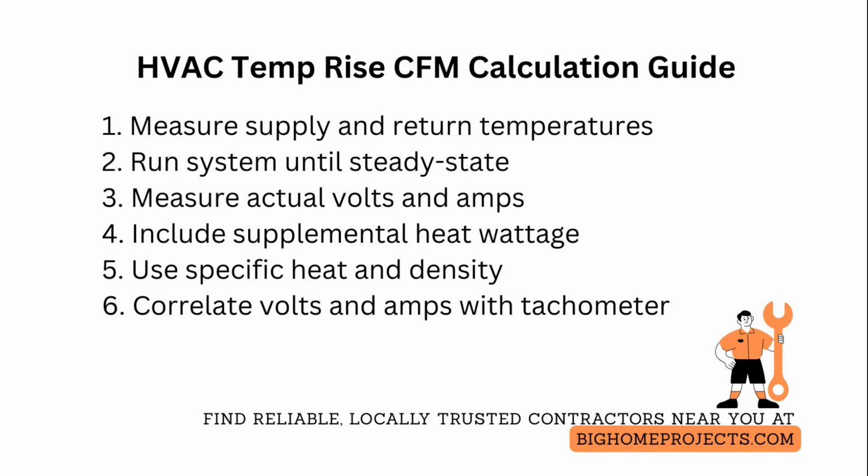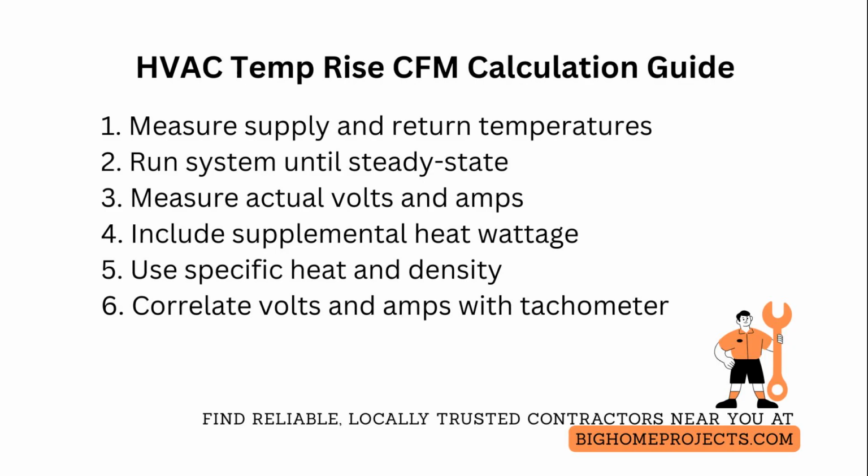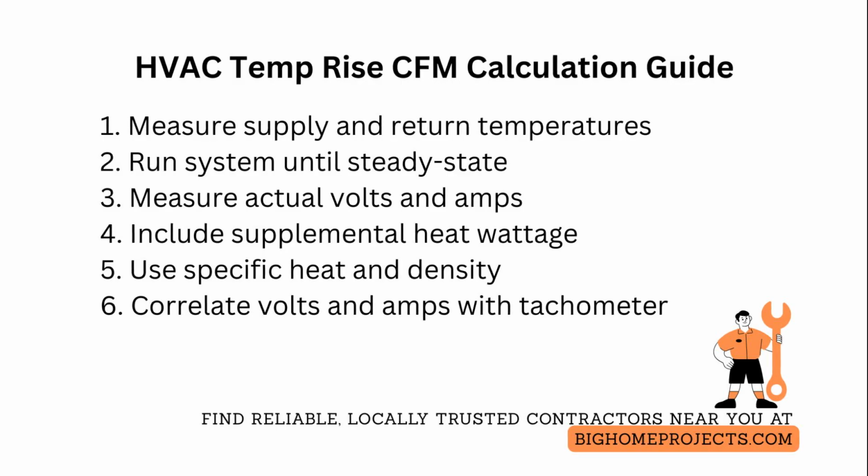Add any supplemental electric heat elements' wattages, from direct measurement or from their stamped rating, and subtract known control losses only if you have validated measurements. Otherwise, include them to avoid underreporting heat.